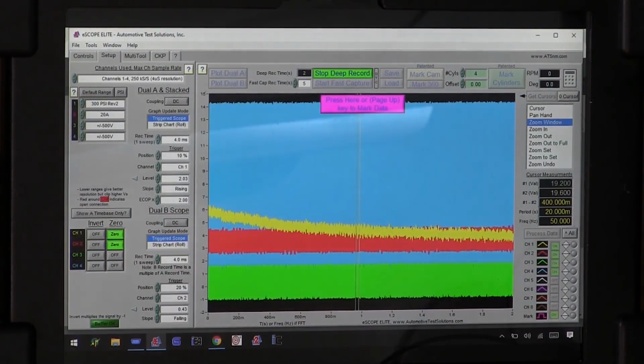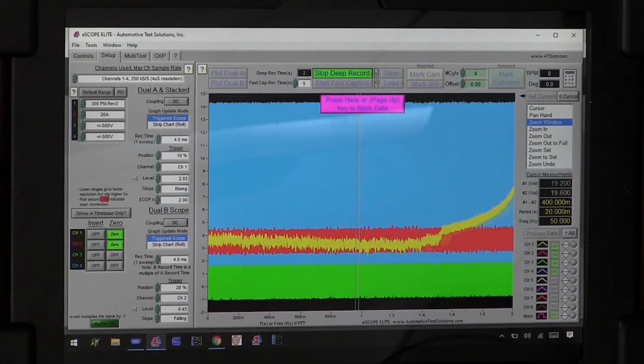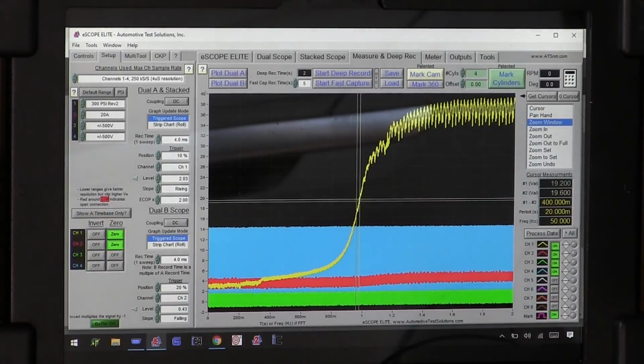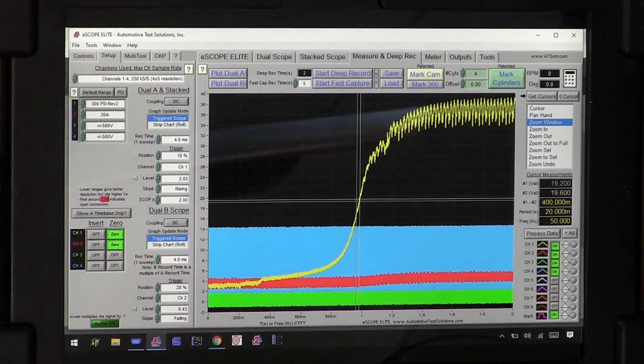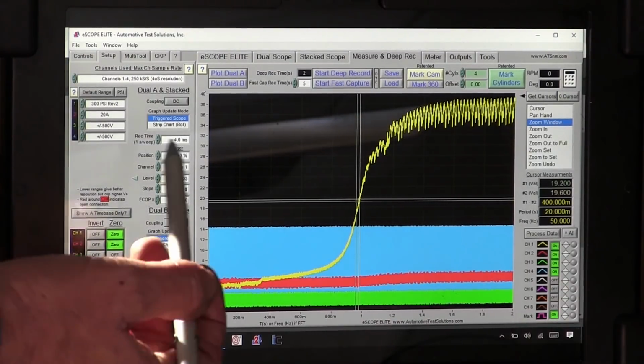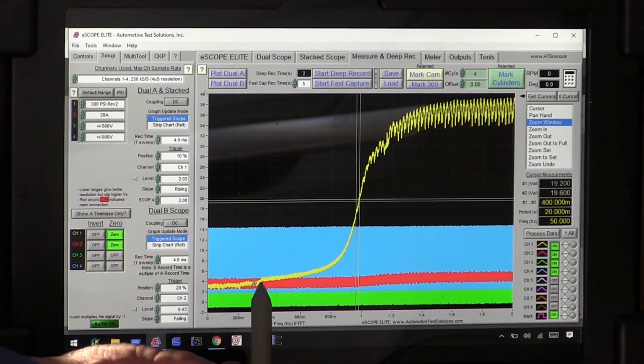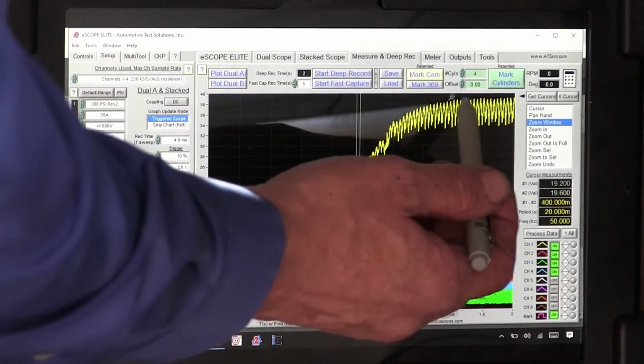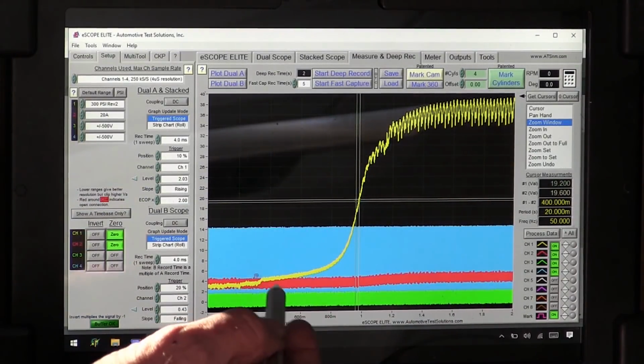Yeah, that pump is full of air, guys. Okay, now you can see where I open it up and it's flowing into the jug. My pressure dropped just a couple of pounds and then rose back up. So I can't maintain pressure.